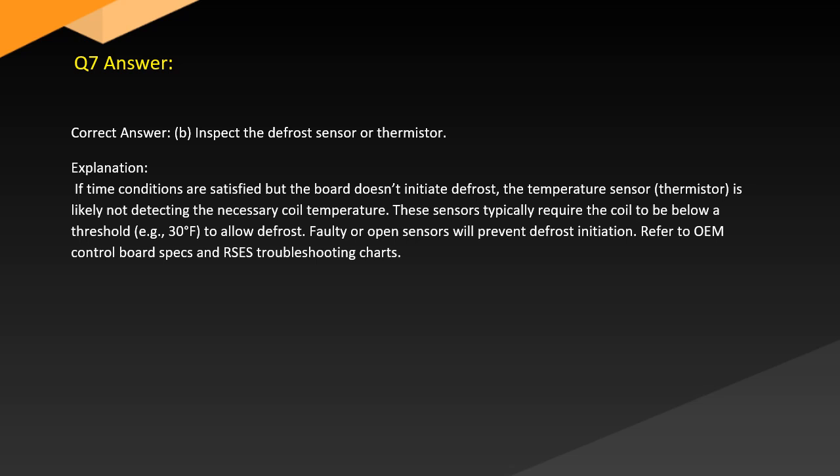Answer. Correct answer: B. Inspect the defrost sensor or thermistor. Explanation. If time conditions are satisfied but the board doesn't initiate defrost, the temperature sensor thermistor is likely not detecting the necessary coil temperature. These sensors typically require the coil to be below a threshold, e.g., 30°, to allow defrost. Faulty or open sensors will prevent defrost initiation. Refer to OEM control board specs and RSES troubleshooting.